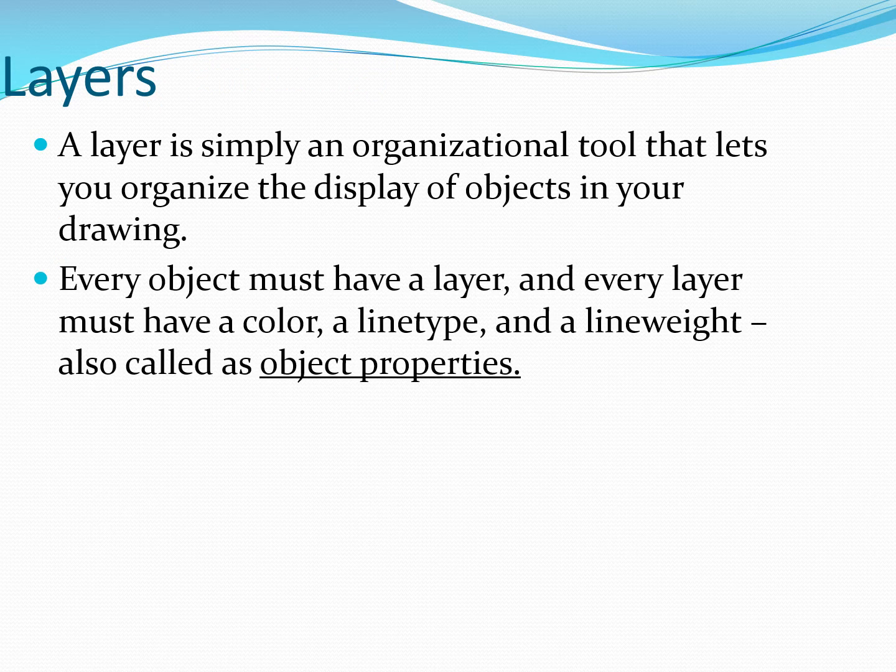Okay, so we go to the layer. A layer is a simple organization tool that lets you organize the display of objects in your drawing. Every object must have a layer, and every layer must have a color, a line type, and a line weight, also called object properties.